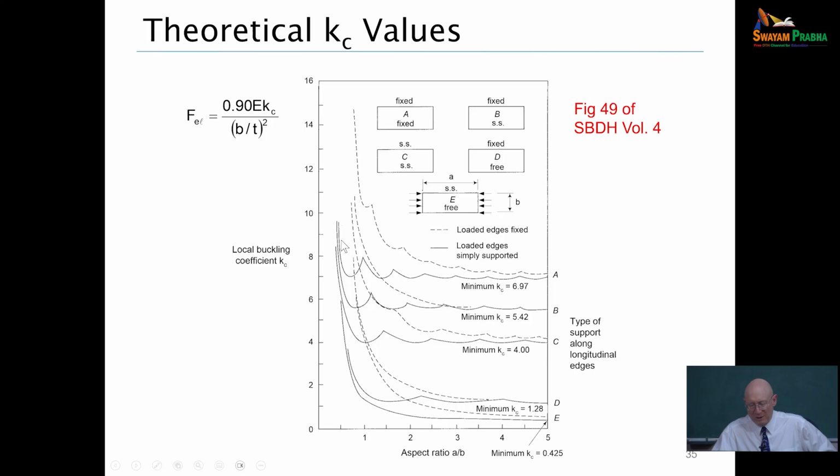If we do an analytical calculation, depending on where we land with the aspect ratio a to b, we could have larger strengths, but we typically design for the minimums that we get out of all this. So at a particular a over b, we have a worst case situation and we just count on that to make our design easy in most cases.